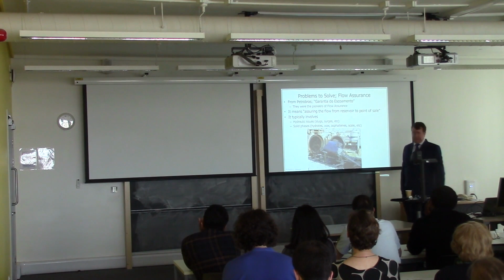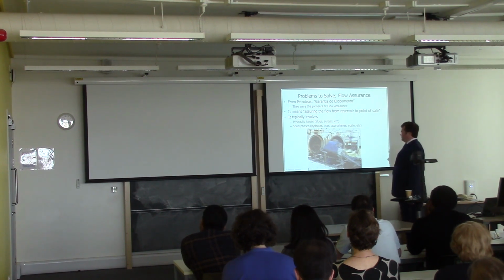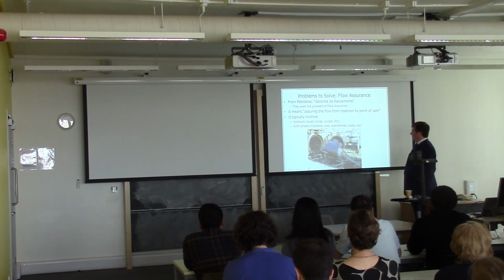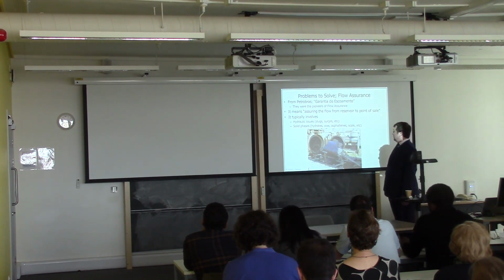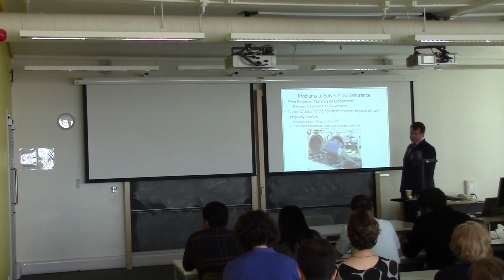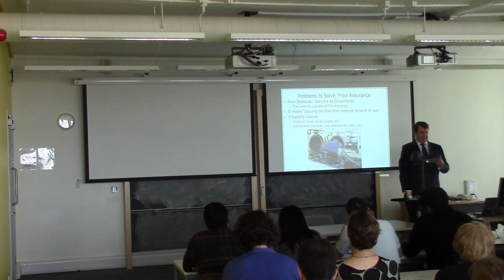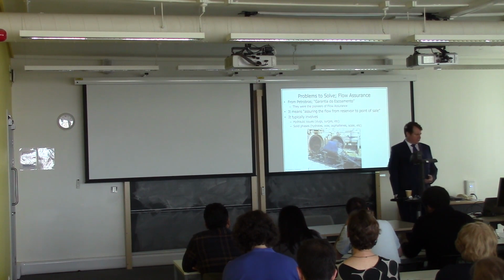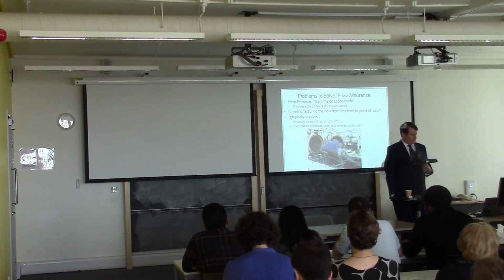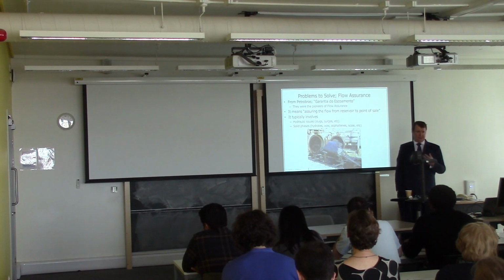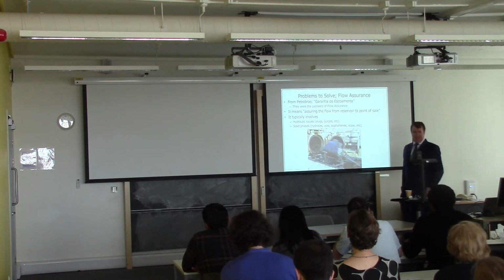Other problems, flow assurance. This is a term originated from Petrobras, and that's what it is in Portuguese, but I'll call it flow assurance. They were the kind of pioneers of this, lumping this together. And really, it's lots of hydraulic issues such as liquid slugs and surges and things like that, but also solid phase issues such as hydrates, wax, asphaltenes.